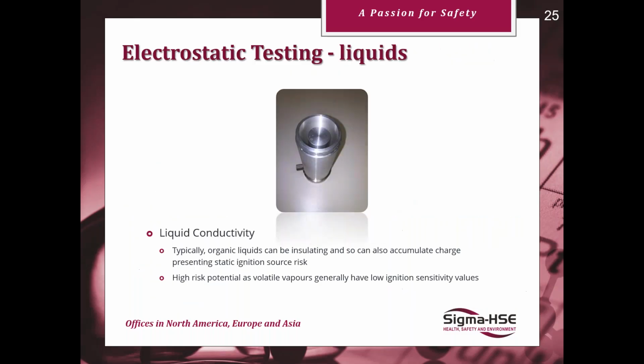Finally, on electrostatics testing, not to forget liquids. We've talked a lot today about solids, but liquid conductivity can also be measured. Typically, organic liquids can be insulating, so they can also accumulate a charge through movement or other charging mechanisms, which presents a static ignition source risk.